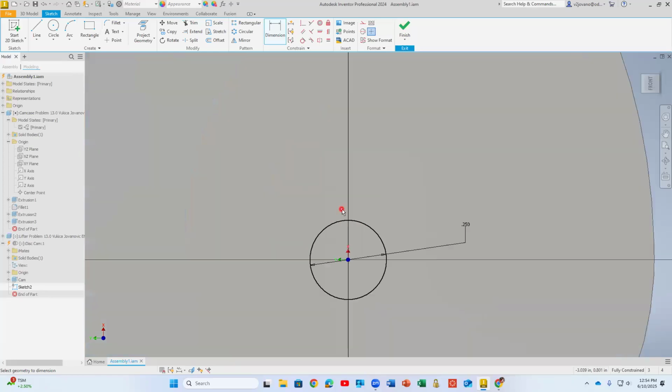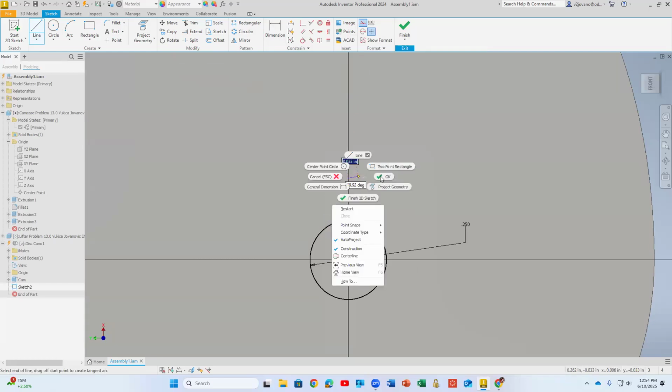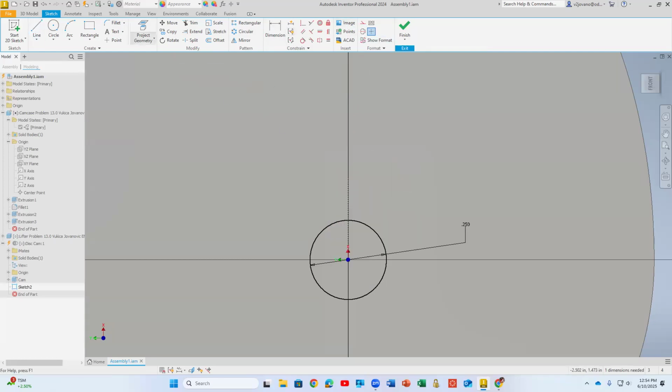Okay, and then we do rectangular shape. But before I do rectangular shape, I really like to prep. Basically, I can put the construction line, and I like this to be symmetric, and then turn off construction line and make rectangular shape, and make it so it's not symmetric. And then when I do symmetry left, right, and middle, I know for sure that this thing will be nice and symmetric, if that's what I'm looking for in this case.